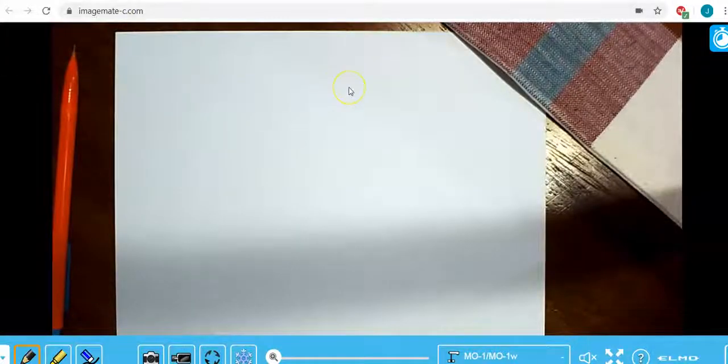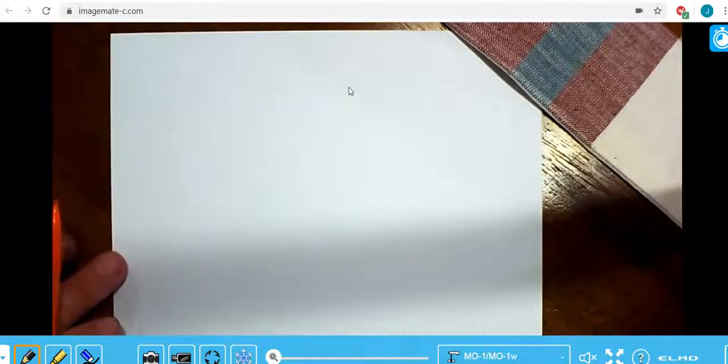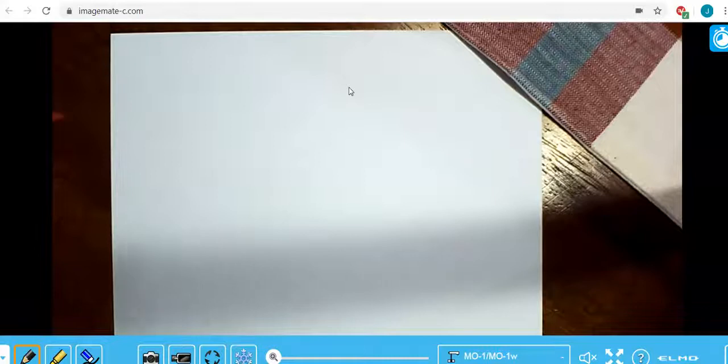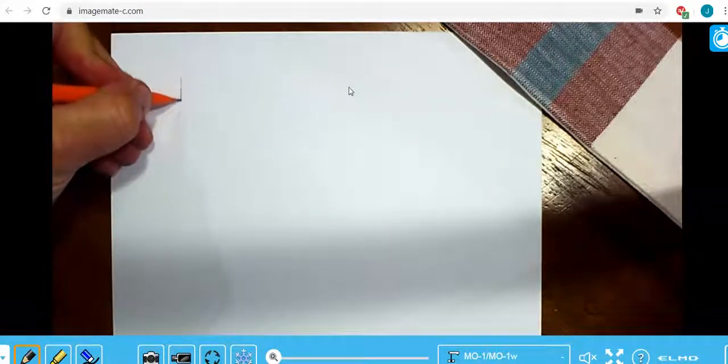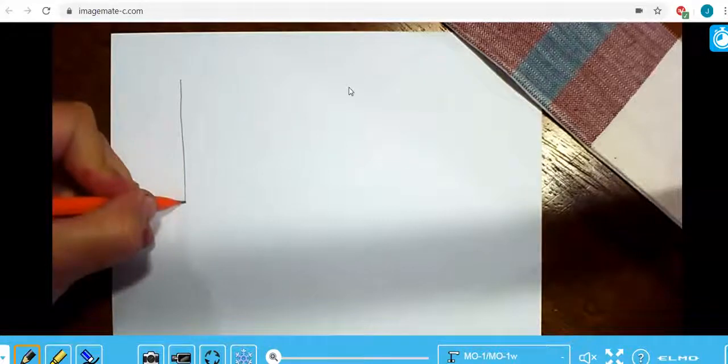So the whole point of this test, the Proctor compaction test, is to create a relationship between the water content that the material is compacted at, and I'm calling that the molding water content. So the water content when you compact the material, and the dry unit weight that's achieved. So this is my symbol for unit weight, and we're talking about the dry unit weight. So I'm just going to emphasize that. And this is the water content during compaction. Okay, so for this test, Proctor developed this test, and